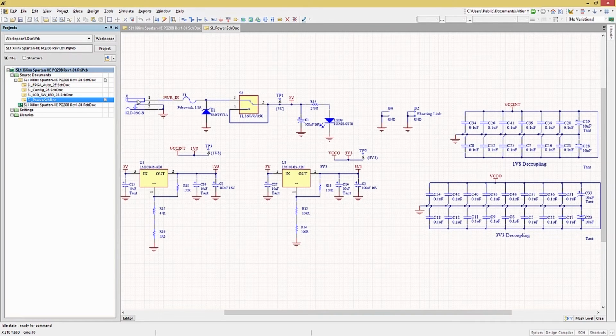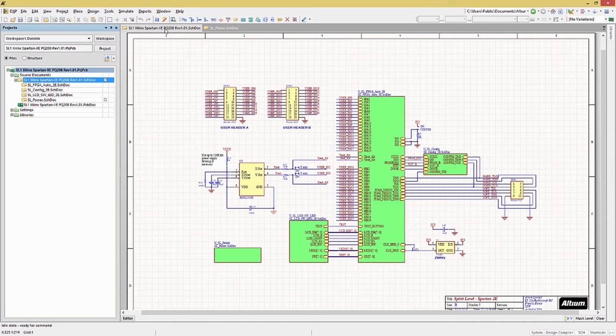Looking at this schematic, we see that it has only one external connector and some power ports. This is why there are no connections at the top level of the design schematic. Power ports are globally connected and therefore do not need to be hand-wired between the various schematic sheets in the design. To return to the top schematic, you can click on its tab in the workspace.